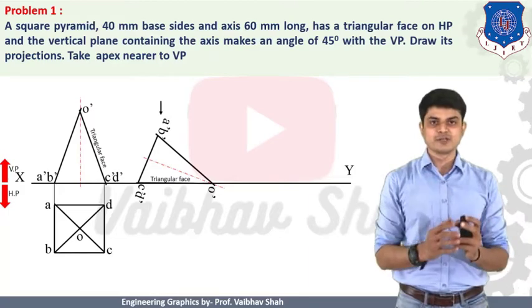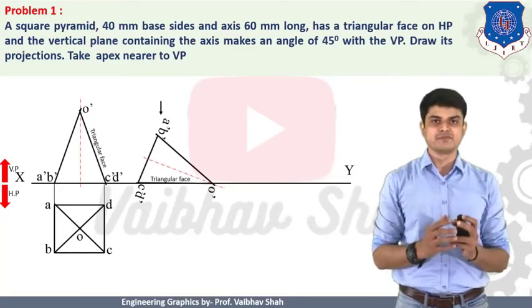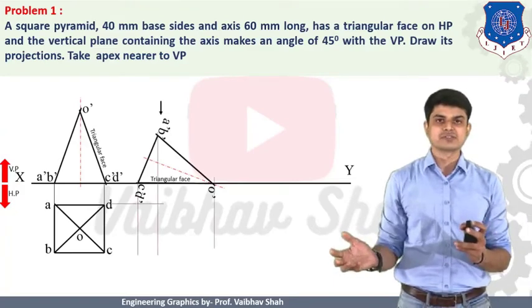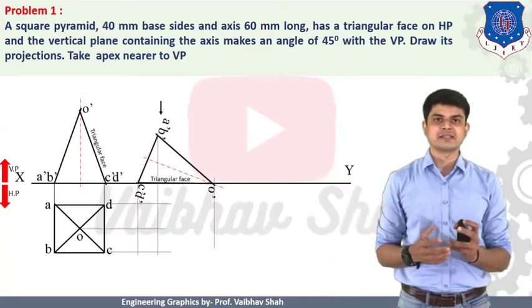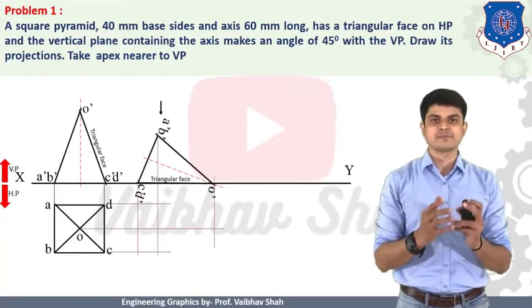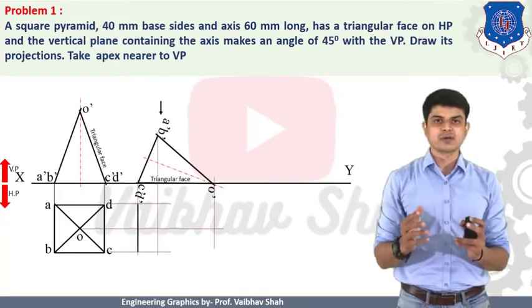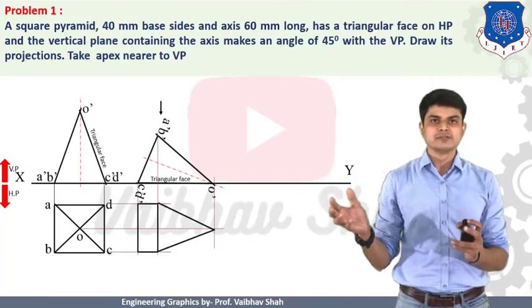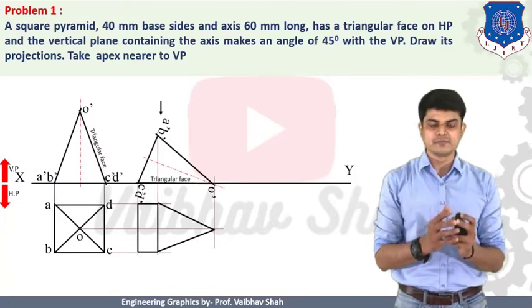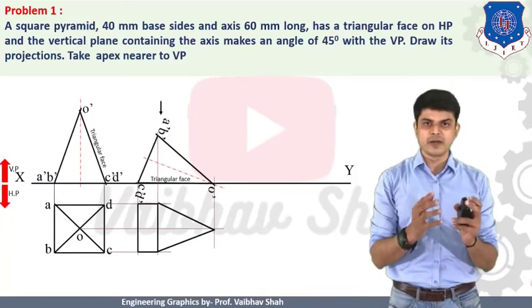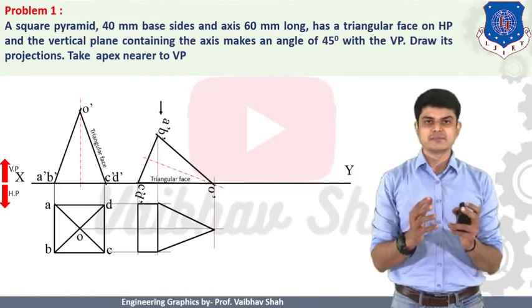And when we observe this object from the top direction, we should draw vertical lines from each and every point like this. And we should construct the horizontal line from each and every point like this. After getting the vertical and horizontal lines, we should find the point of intersection and construct our element. So this is nothing but our element constructed. So this is our final element. Very easy, as you can see. So let us analyze the object in order to find the hidden line possibilities.